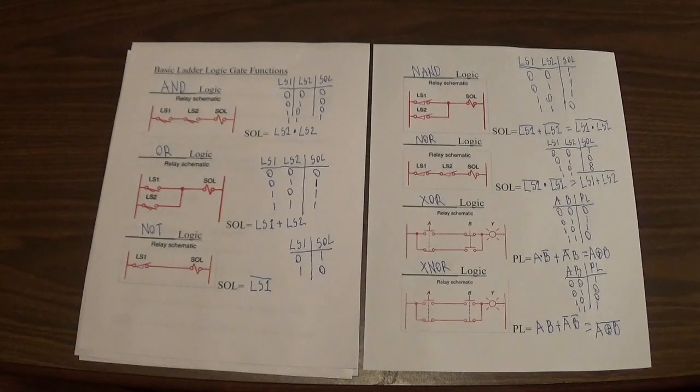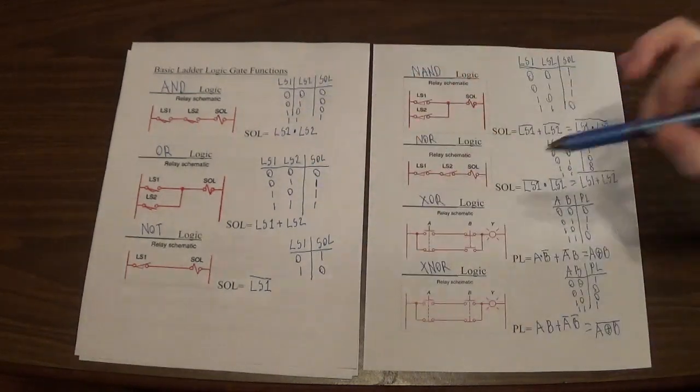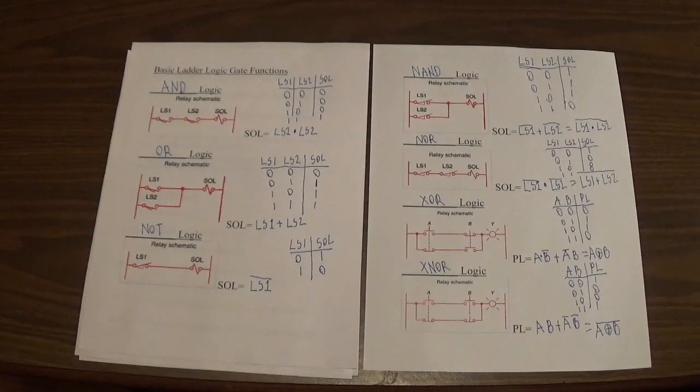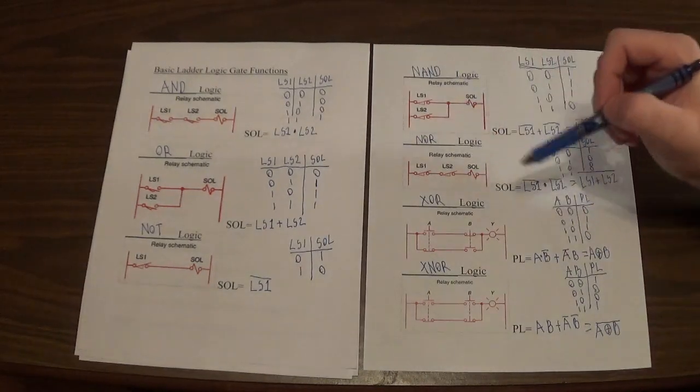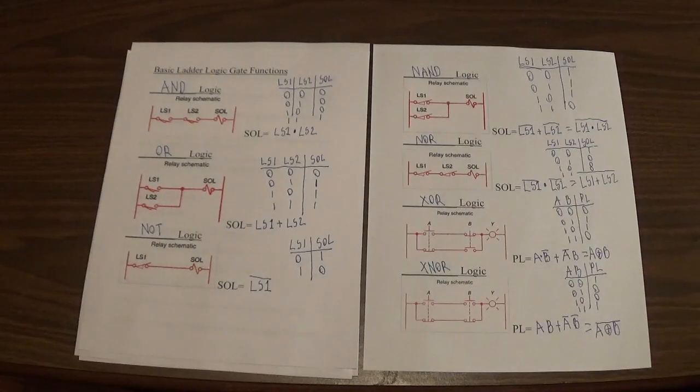All right, so you can apply this to any ladder logic diagram, just looking for these different connections. So this is all the logic functions and the examples of how those switches are connected to get those different examples. These are individual ones that I pulled apart. Of course, a ladder logic diagram is a big long diagram with multiple lines in it, but you can pick apart these connections to better understand how the outputs are supposed to behave and therefore be able to troubleshoot them more efficiently.